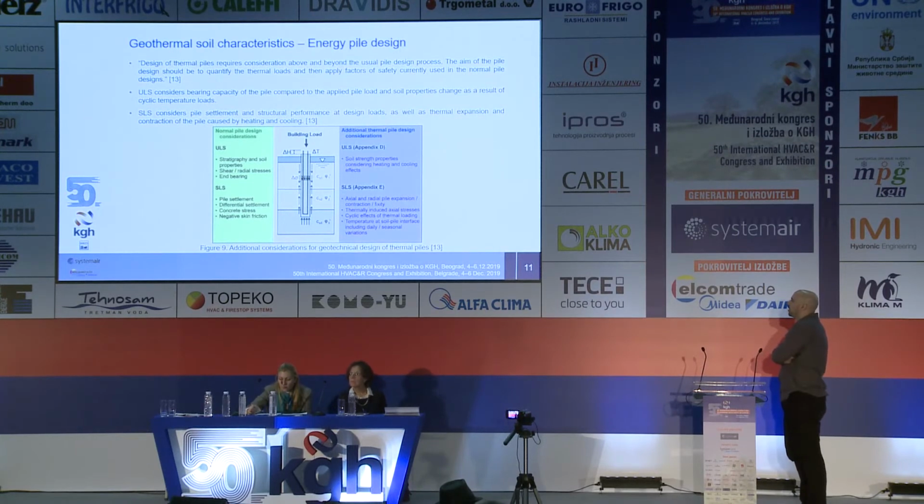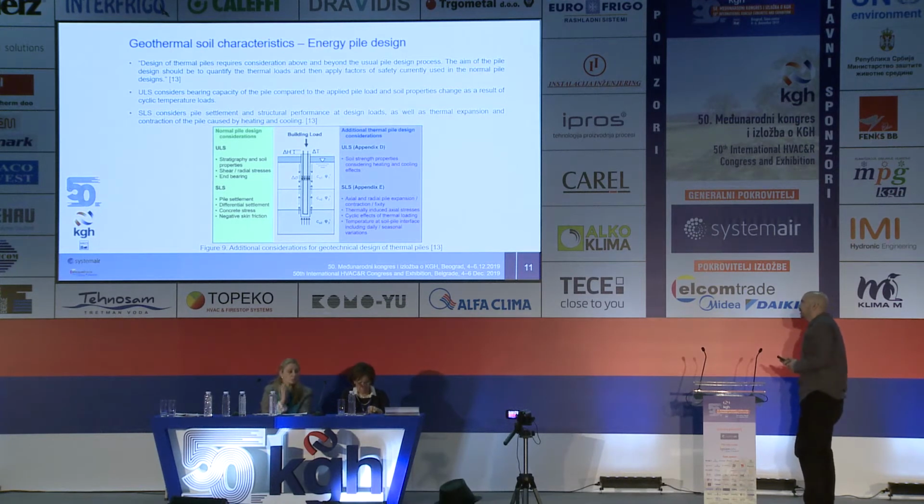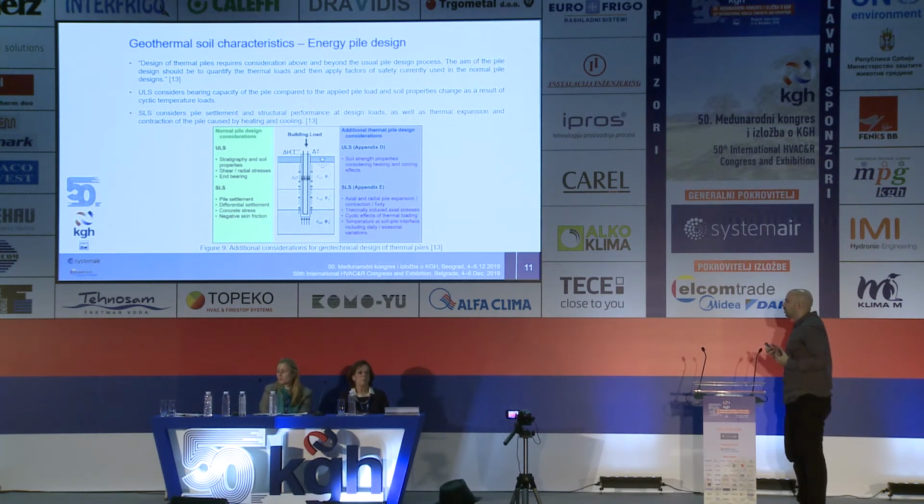SLS considers pile settlement and structural performance at design loads, as well as thermal expansion and contraction of the pile caused by heating and cooling. So what does that mean? That means that we have certain deformations and stress changes in our piles because of the change of the temperature.